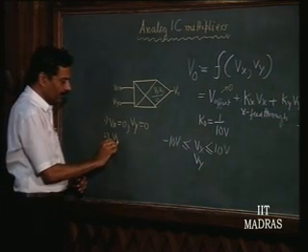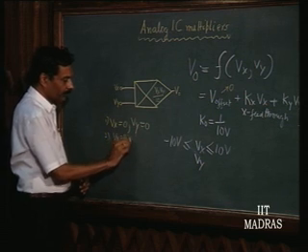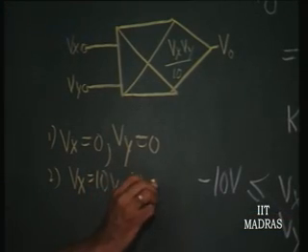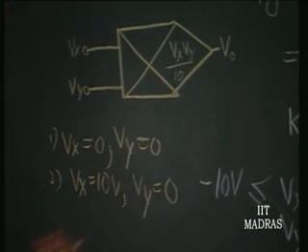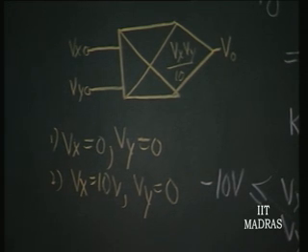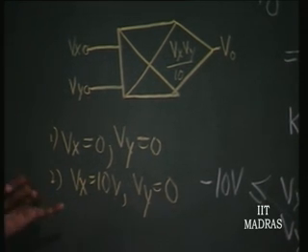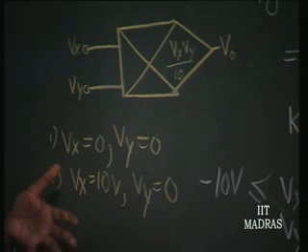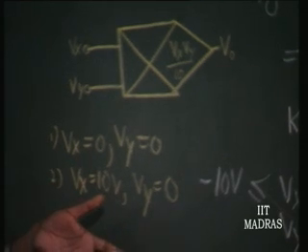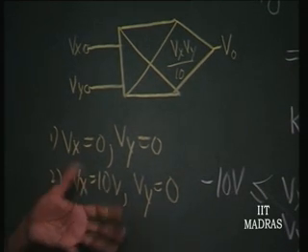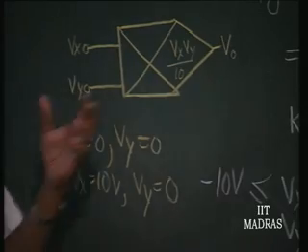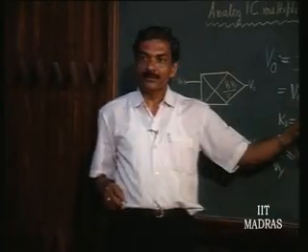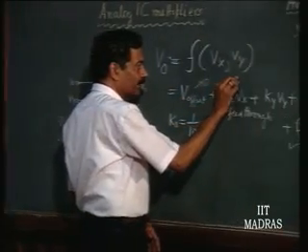Then we make Vx equal to 10 volts, Vy equal to 0 volt. Then any output that comes must be due to x feedthrough, and that will be coming through as its maximum error output. That has to be adjusted to 0, not by adjusting Vx, but by adjusting a means of making Kx equal to 0. So, Kx adjustment is done that way.